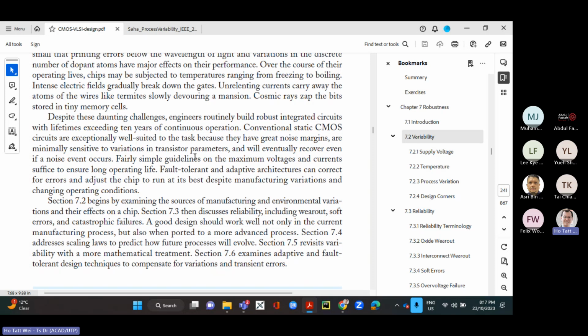Right now, I think the state-of-the-art process technology is 3 nanometers. That means the gate length is roughly on the order of 3 nanometers. Of course, it's folded up like a FinFET structure to get it a bit longer, but the device size is 3 nanometers, and you're actually down to several molecules type of dimension, because molecules tend to have dimension in the order of angstroms, which is 0.1 nanometer. That range of size is what molecules are, right? So you're down to the level of just a few molecules per device. So it's going to be pretty difficult to really control very precisely what we can fabricate. So process variability is going to be here to stay with us.